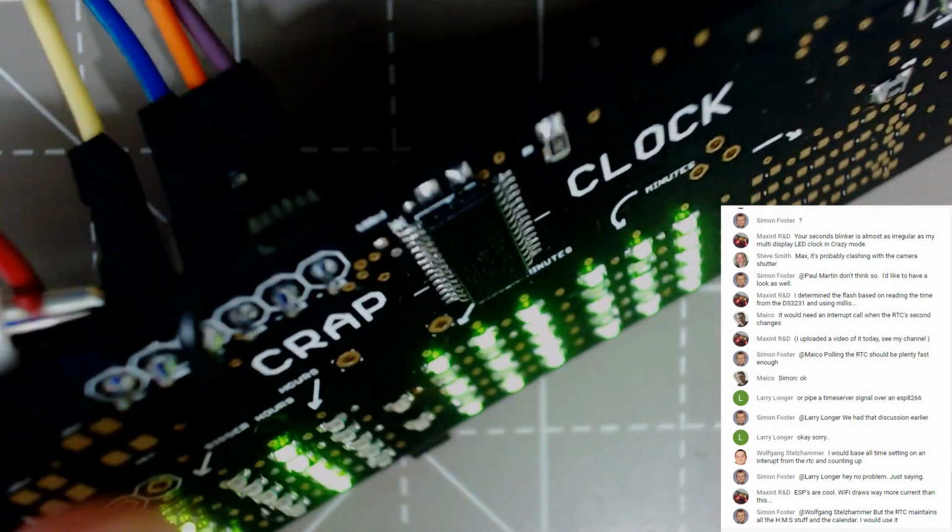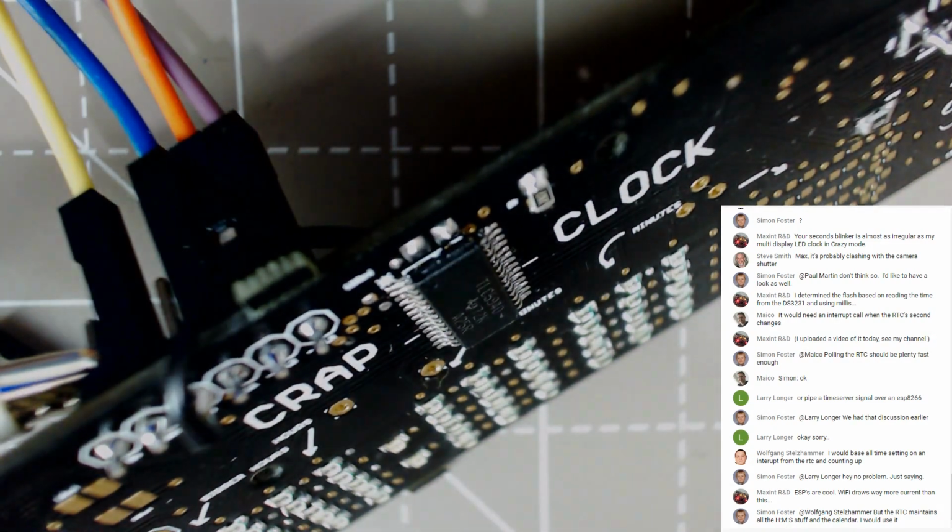So with all of those LEDs lit, which is 1 row at a time, and microcontroller running, everything else on board running, including the DS3231 and the 74HC595, we are pulling 35 milliamps, peaking at 37 milliamps. So I wonder if all those LEDs were off, how much we'd be drawing, but it's probably about 10, 15 milliamps for all of those LEDs that are on. So it's not low power, it's still a fair amount, but